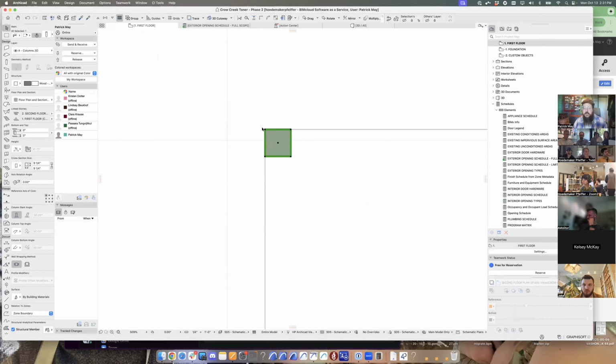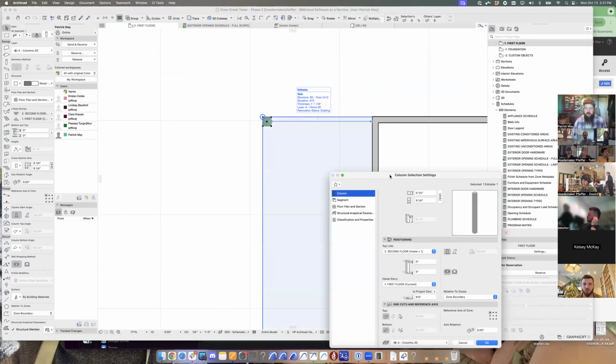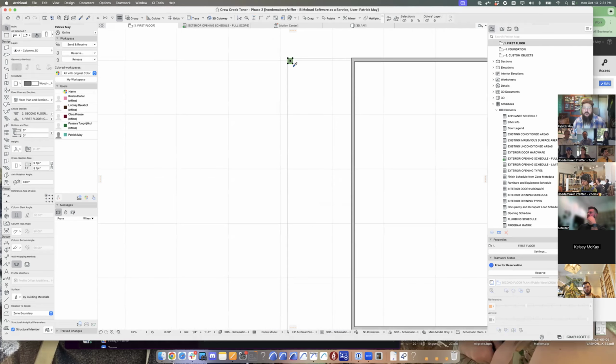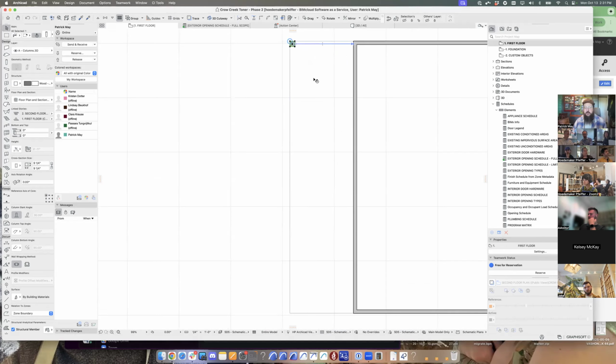Because I put that origin point on the corner of that slab, when it grows or shrinks, it grows and shrinks from that corner. It takes a little bit of extra time to define that and place it, but it means that when the design changes, I know that that's all going to get updated with the design. I refer to this as future-proofing your design, taking these little steps to get ahead of the curve because you know that the design is going to change. You want to be fluid with your ideas, so adjusting those settings as you go is going to be a lot more efficient.